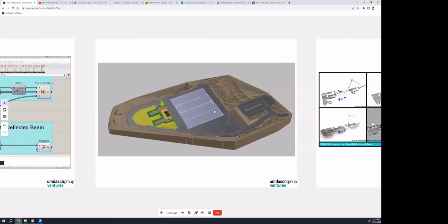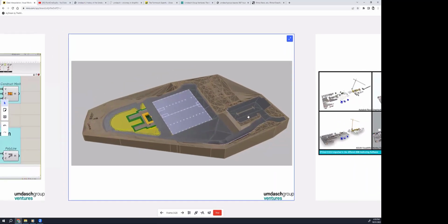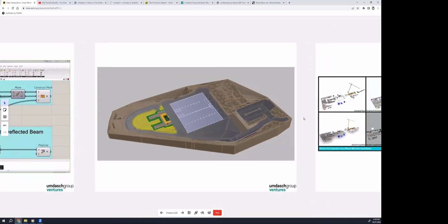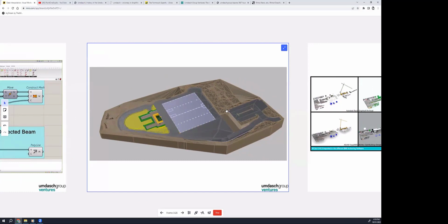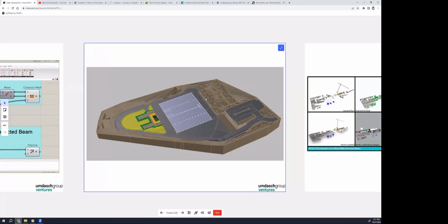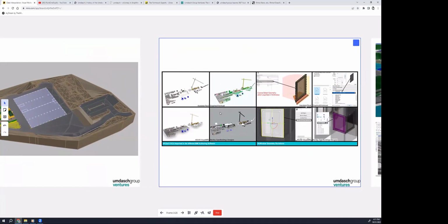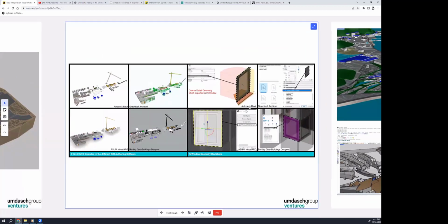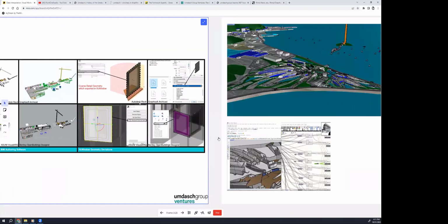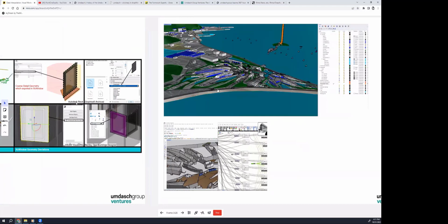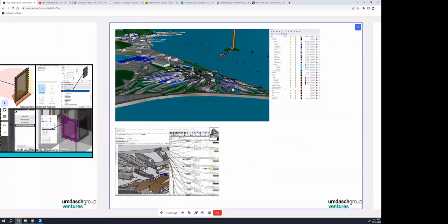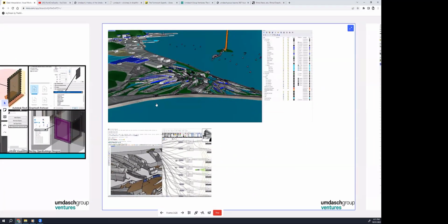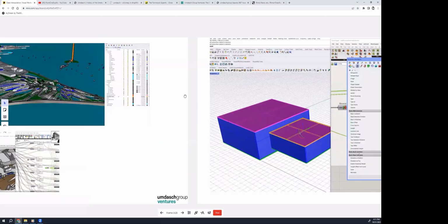And also we have a civil model as a use case. In this case, I use particularly VisualARQ to use Rhino geometry and information to export as an IFC. And I'm going to criticize a bit the IFC model, which is not perfect for different applications. And for this reason, I think Rhino is a really great tool to bring different geometrical input information and also non-graphical information to interpolate this metadata to other platforms.